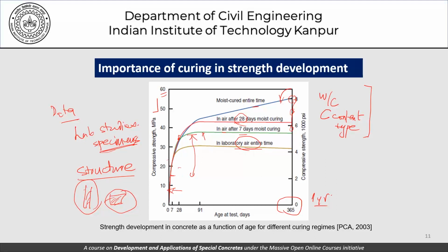So that's another engineering approximation that we make in all of our concrete engineering discussion, where we try to study a lot of concrete properties using laboratory specimens under certain conditions which are standard. And that's why standardization is very important. That under standard conditions, which for example in India would be underwater at a certain temperature for 28 days, try to do that. So that really gives you just the potential strength of concrete from a specimen point of view.